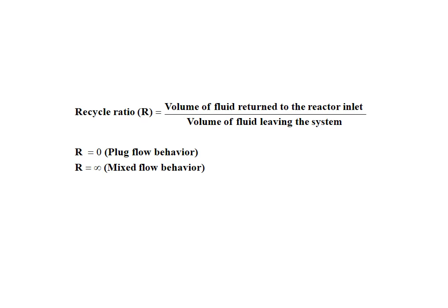So we can calculate the recycle ratio R, which is equal to the volume of the fluid returned to the reactor inlet divided by the volume of the fluid leaving the system. Here, if capital R is 0, then it is plug flow behavior, whereas when capital R goes to infinity, it is mixed flow behavior.